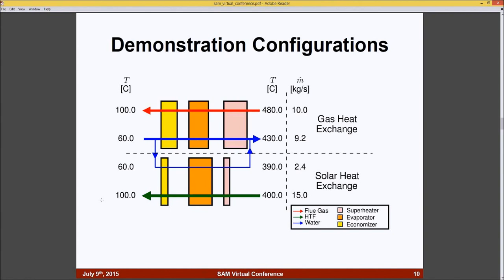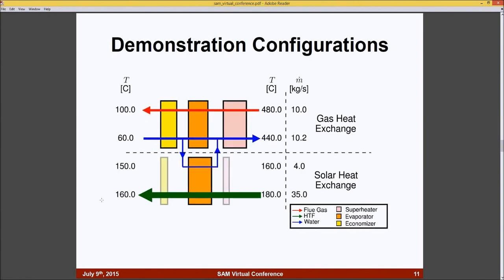But something that we might look at doing is exploring an alternate water flow path configuration. If we keep the same heat exchanger layout, but bypass the economizer and the superheater, and only use the evaporator in the solar thermal section, the temperature difference in the water stream on the solar thermal side goes down a lot because it's essentially only handling the approach temperature inside the evaporator.